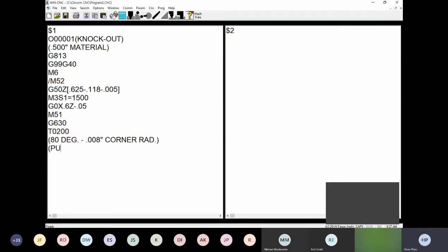Let's say we put 4 in the P column in the data set. That means we're going to use the OD turning tool and the tip direction is going to be number 4. So the operator can read this and put it right away in there with the radius 8,000, and the direction is going to be 4 because we're going to use the tool nose radius compensation later on.